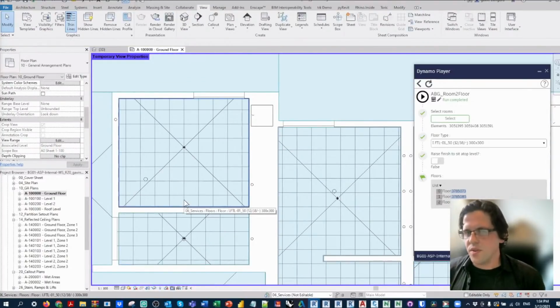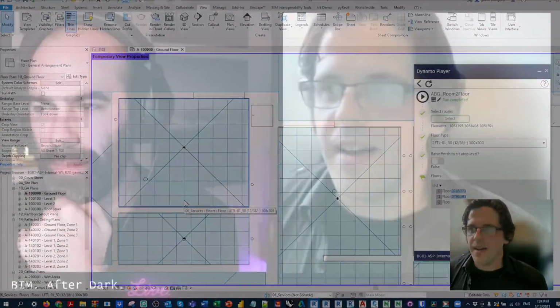And I only did 3 floors there, but I used this the other day on a hotel that I was doing for a client, and I did 11 stories of floor finishes in, I think, about 12 seconds. All the carpets, all the tiles, all the set downs were automated. So I just pressed a button and came back to them in about 5 minutes.